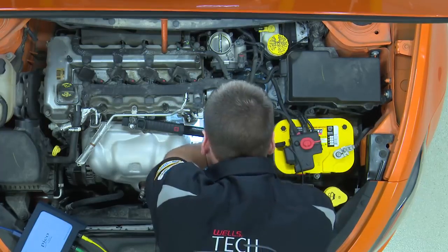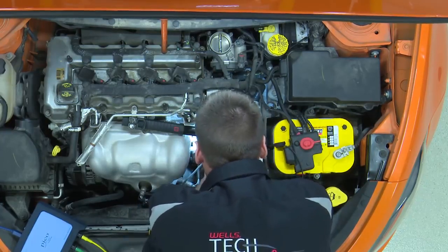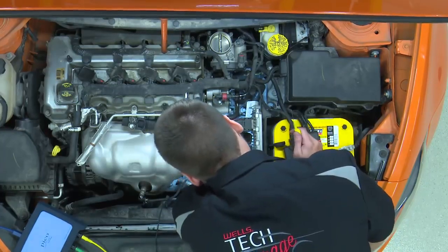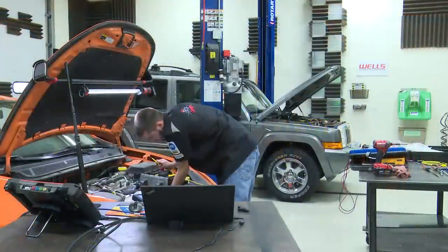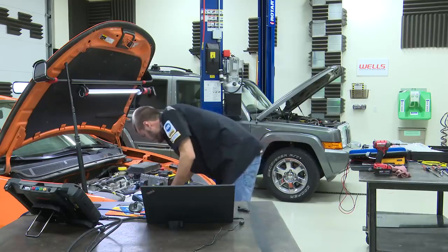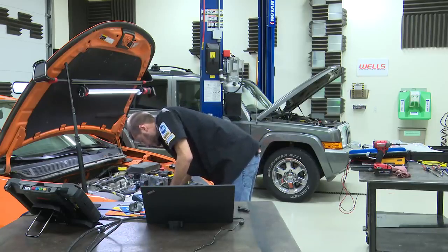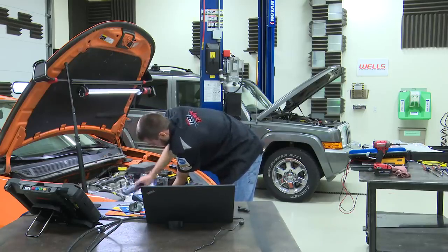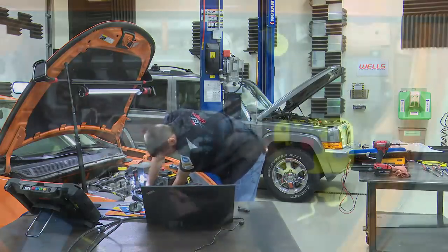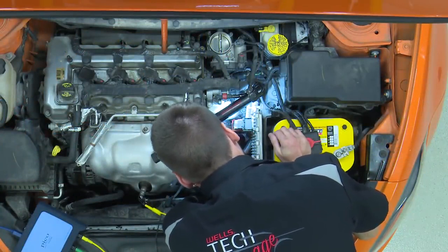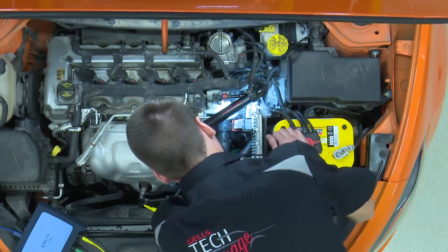All right, so just get our last pin in here, maybe. I'm going to plug it in. Might be easier to get to that last one. Be careful if you guys are using T-pins, because if I was using T-pins on here right now, I probably would have just shorted some of my connections together. All right, these back probes work awesome. You could pierce the wiring potentially. I plan to do a video in the future showing the differences between piercing and probing, but that'll come at a future time. And for some reason, this does not want to plug back in.